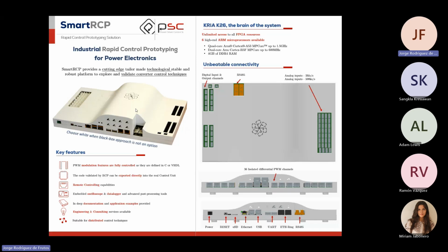It's a Zynq, so it includes a quite big FPGA and also 6 microprocessors. 4 of them are for application, A55, and 2 of them are a couple of Cortex R5, microprocessors for real time. Today, we will be using the FPGA part, but also one of these Cortex R5 processors.